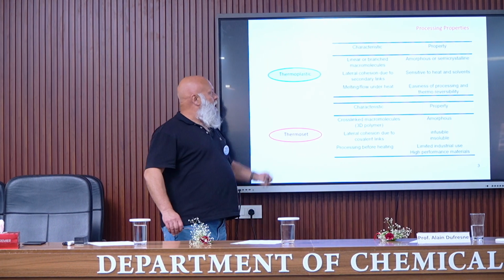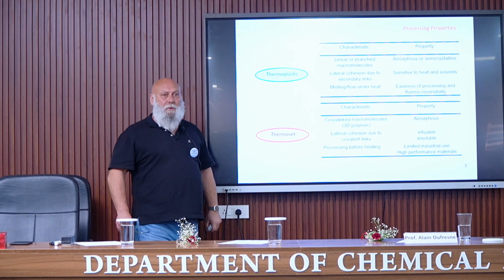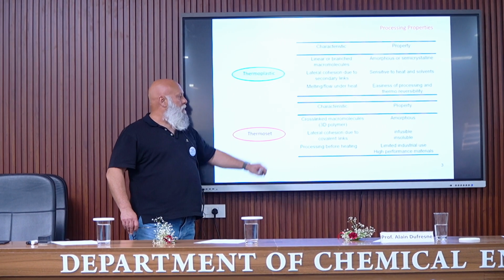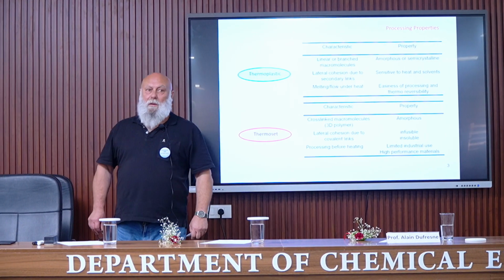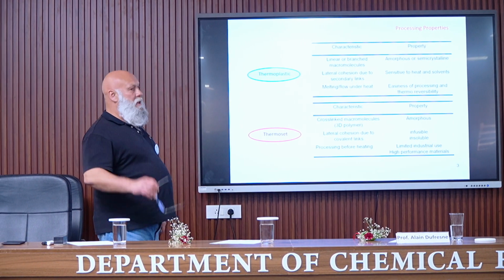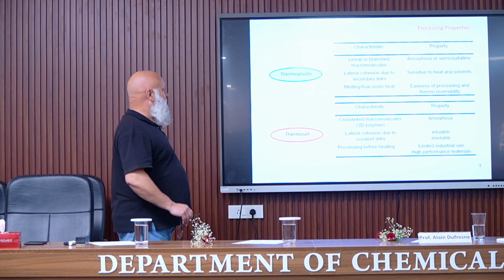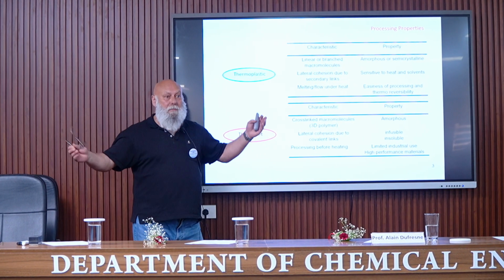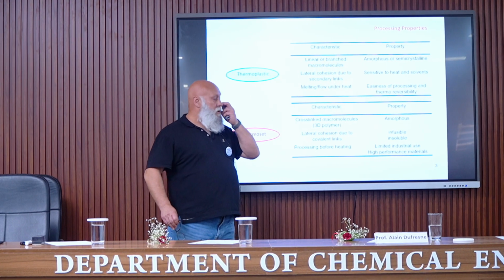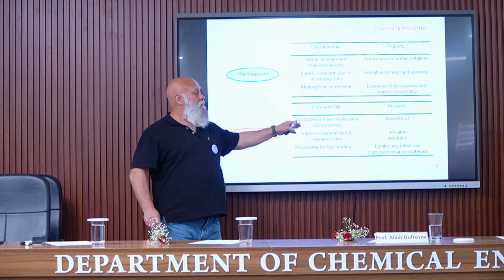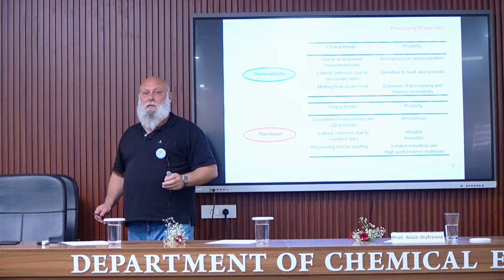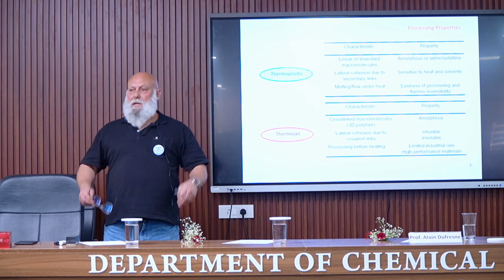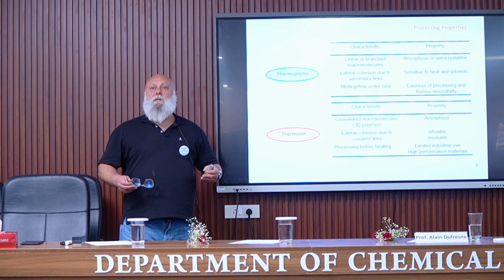Now regarding thermoset polymer, we are considering cross-linked macromolecules. So meaning that there are some covalent bonds between these macromolecules, meaning that the molecular weight can be considered as very high. It's a 3D polymer. In this case, you can imagine that the diffusion of the macromolecules when cooling the material is impossible, meaning that these materials cannot crystallize and they are always amorphous.